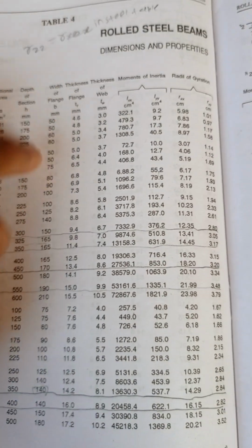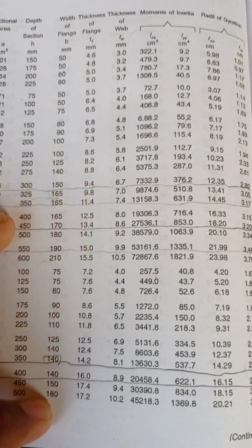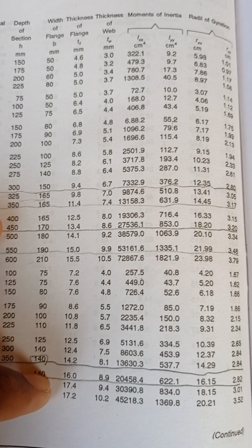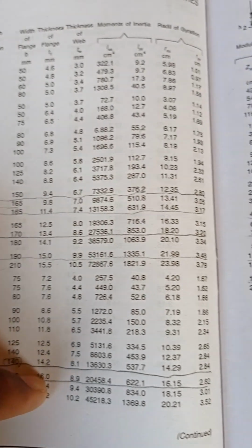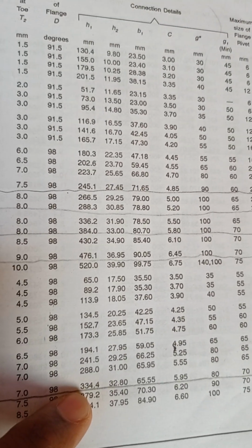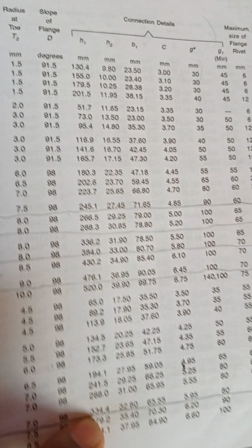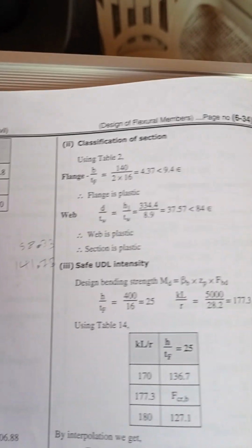TF, which in this case B here is 140, TF is 16, and the H1 is 334.4. So that's what you need for section selection. Using table number 2 from IS code,